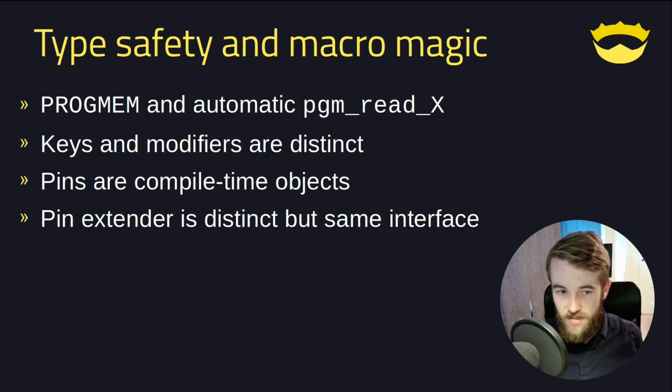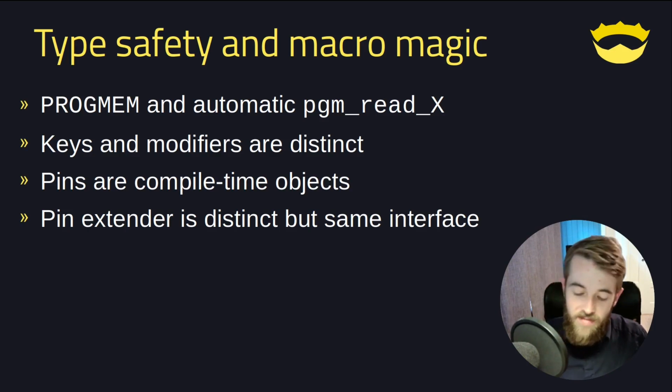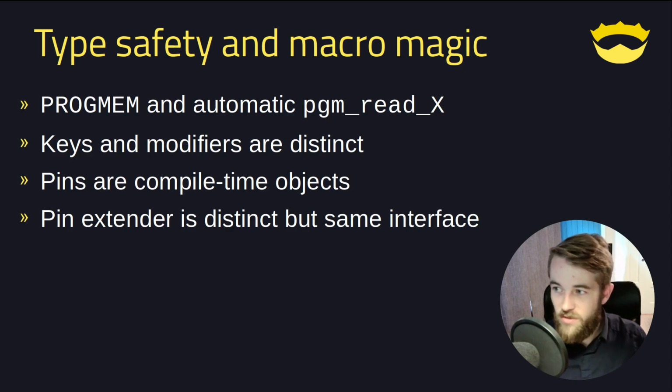As I mentioned, this compile time rewriting really cuts down on program size and also speeds up our program. And one really fun thing I noticed was that I was having some weird issues, and it turned out that it was too fast. So I configured the pin and I tried to read from it, and it didn't have enough time for the voltage to stabilize in the matrix. So I got bogus readings.